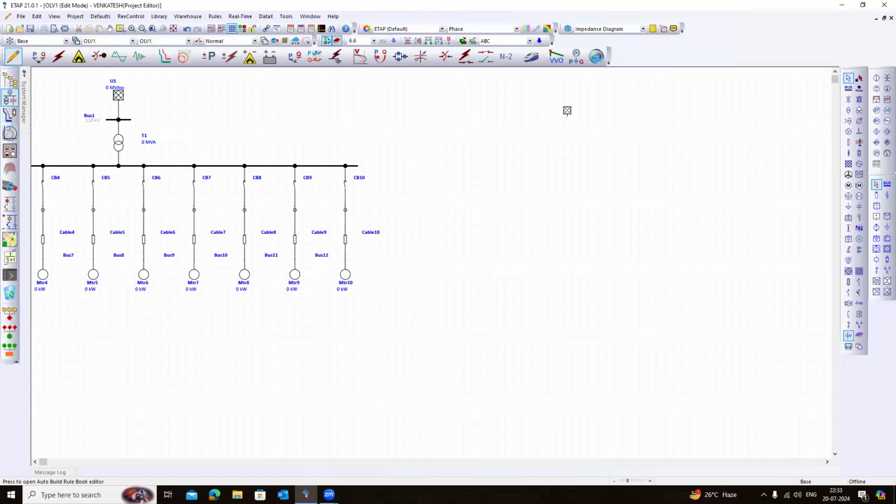Let's suppose I'm creating this one, and I'm connecting a bus, and here where is the breaker, the HV breaker, and here is this element, and you can click on the relay itself. This is connected to the relay, right? And after this, let's suppose I want to connect to the transformer, so click this transformer, connect to the bus.